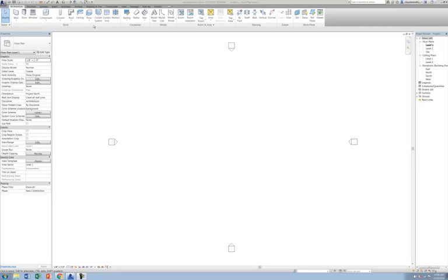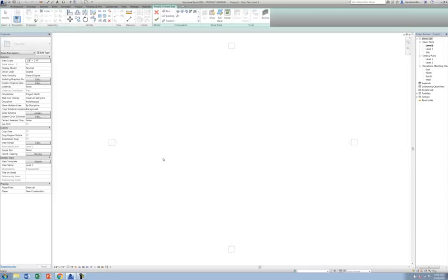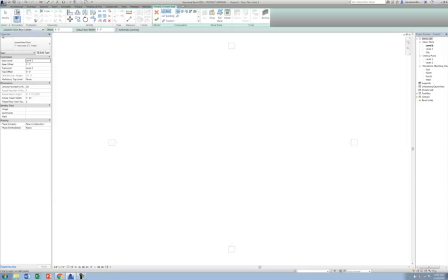So just to dive back into the stair structure a little bit, I'm going to start drawing one. You can see again by default, it gives you the desired number of risers to get from level 1 to level 2. I'm just in a new architectural project here, by the way. And here you can define custom tread depth, and the actual riser height is going to be some numeric value, basically dividing the height between level 1 and level 2 by the number of treads you want. And as you start sketching, again, it's a pretty smart tool.